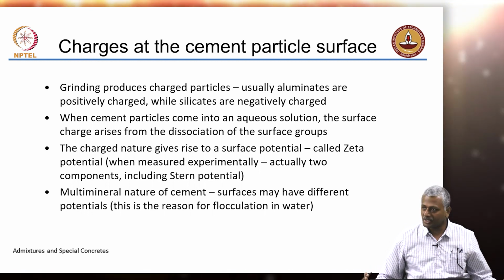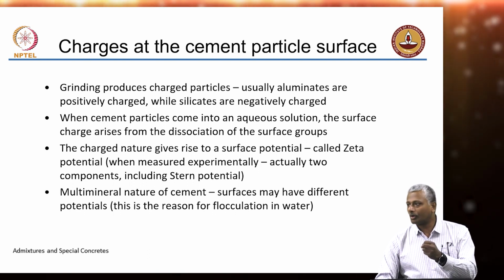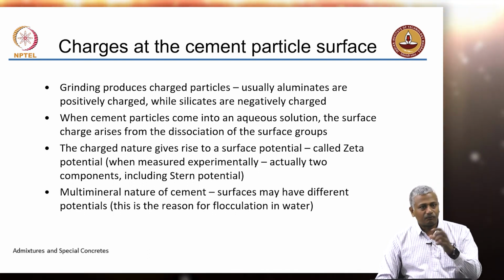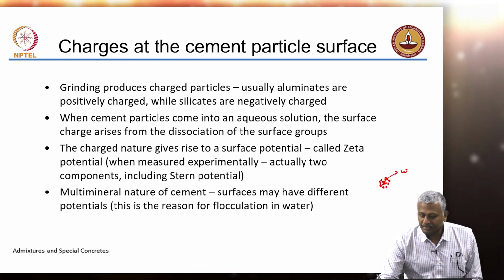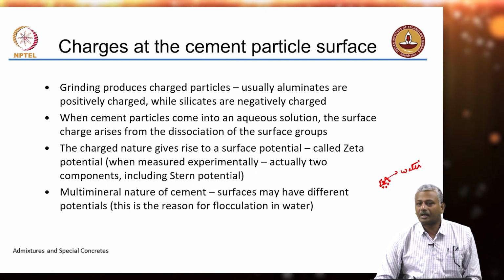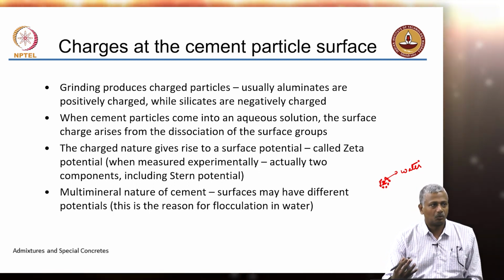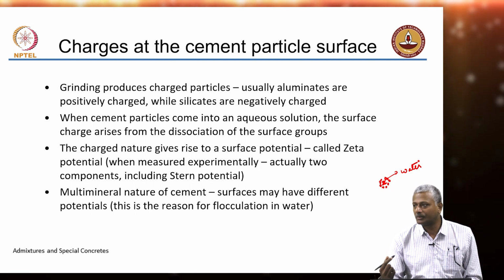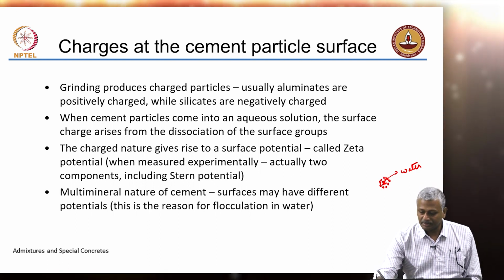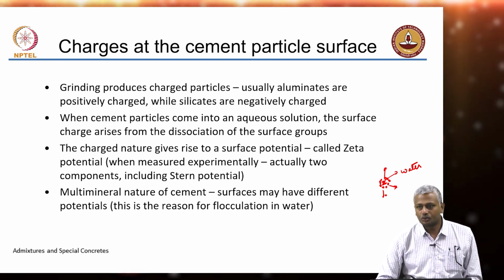As I said, when you have opposite charges, particles are coming together and forming flocks. And when you start forming flocks, what is going to happen is these flocks or bunches of grains, right, they are attracted together and they start trapping the water inside. And obviously to produce workability in your concrete, you need the water. The water creates this flowability. So if you are trapping the water, it is not available to create workability, right. So what we need to do is ensure that the particles are getting dispersed, and for that we use the superplasticizers.